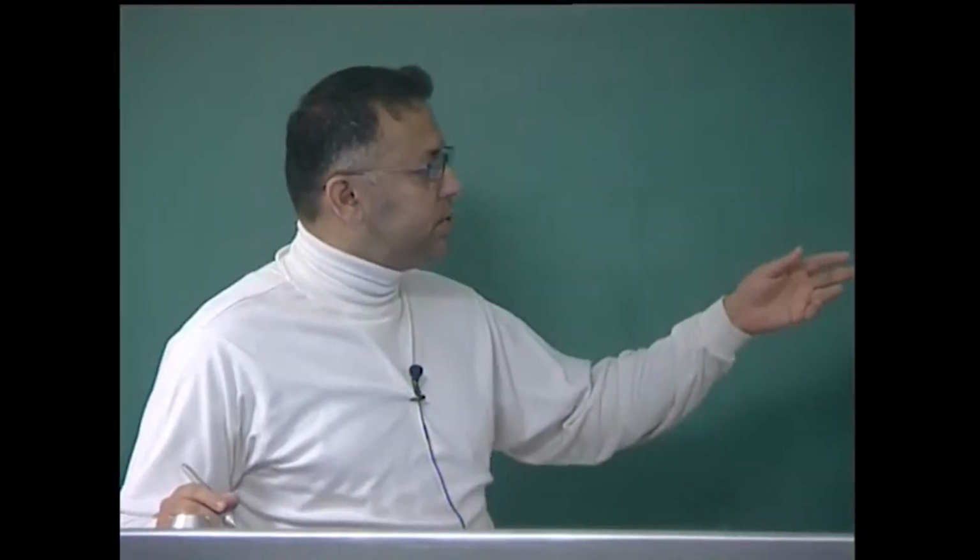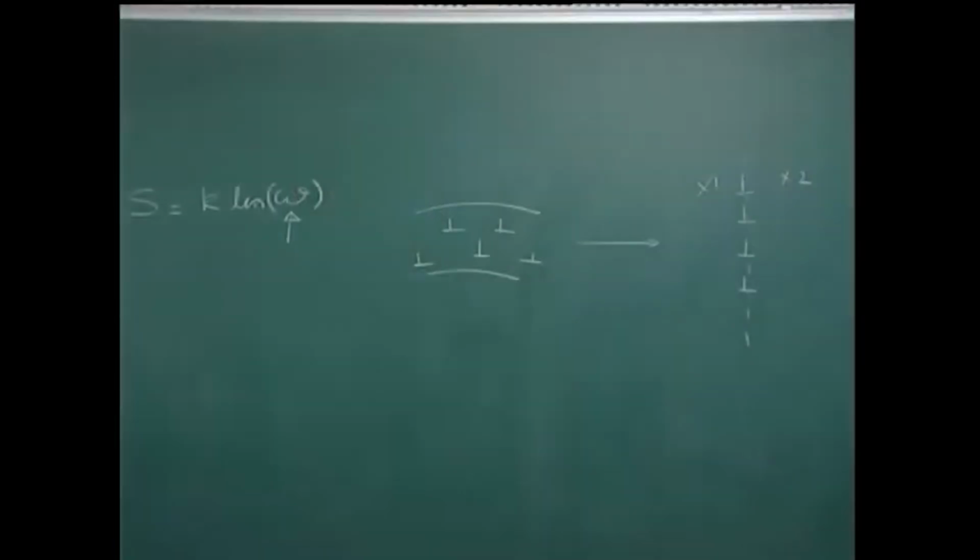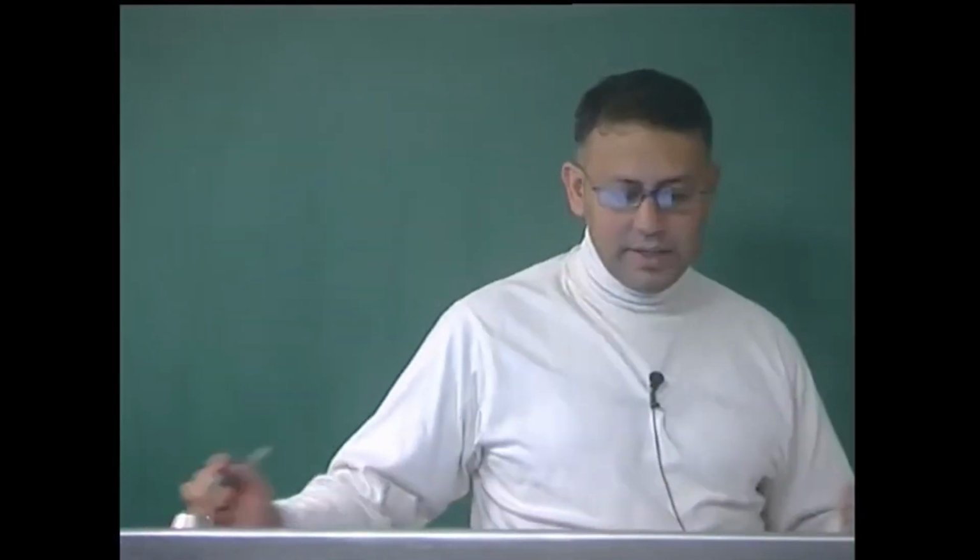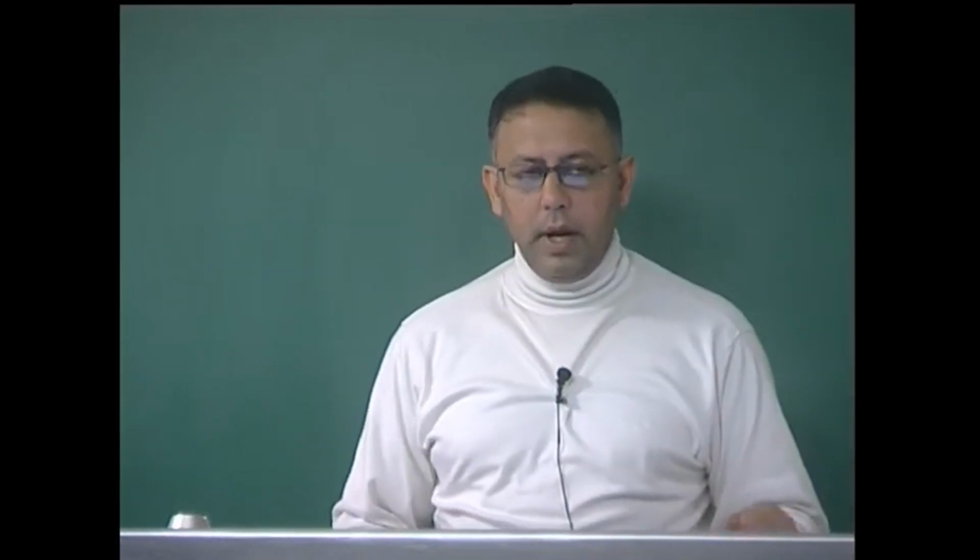Now, this is in some sense an extreme form of defect association, wherein all the dislocations have been arranged one below the other and they are associated with one another to form a low angle grain boundary. But for such a motion to occur, there needs to be some kind of activation, which could be a thermal activation, as in the example of formation of the low angle grain boundary. And of course, I pointed out that the long range stress fields help in such a process to take place.